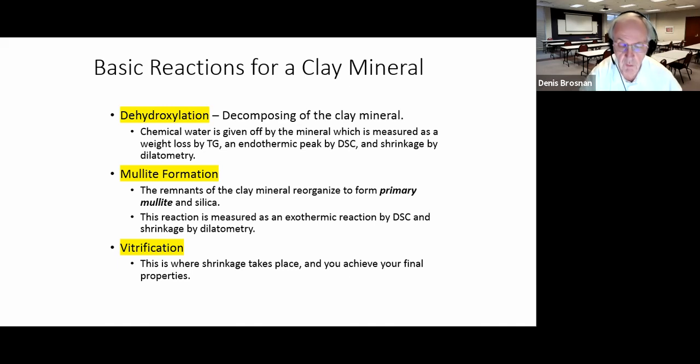And we form a few percent liquid that serves as a cement. It bonds the residual particles together. These residual particles include dehydroxylated clay and quartz and other minerals that may be present. They're cemented together by the crude glass that's formed in firing.